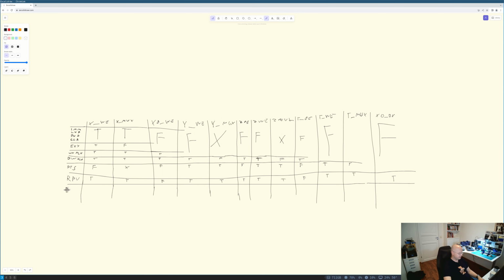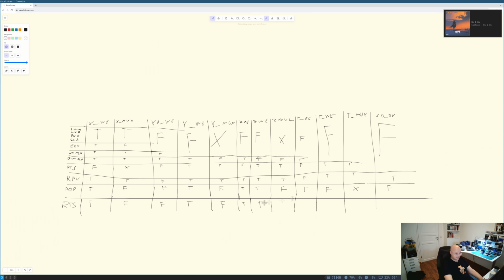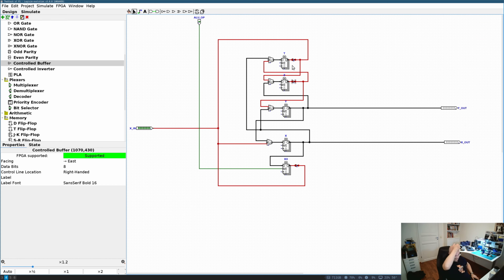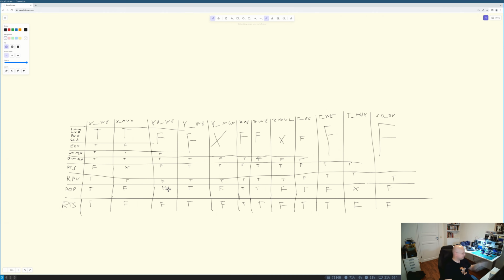I'm going to write the whole truth table for all the operations and all 12 control pins. And actually, I don't have just real operations here, because I will have things like unary ALU operation and binary ALU operation. That's not an opcode, but just a mapping for some opcodes. And I need to distinguish unary and binary, because for both ALU operations, X0 is set from X, but for binary operations, a pop operation should also be done.